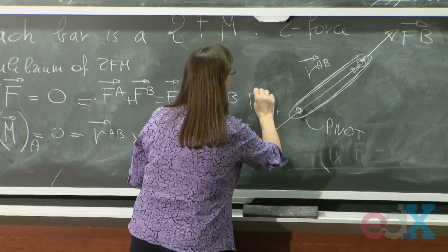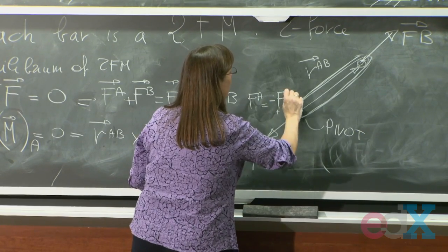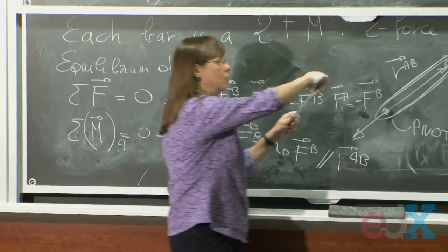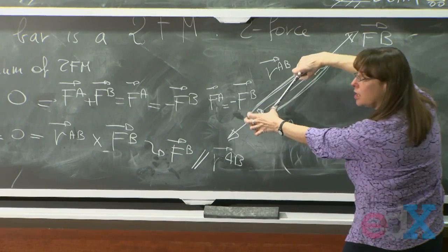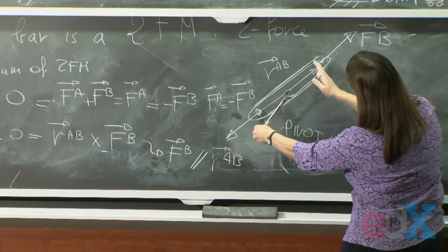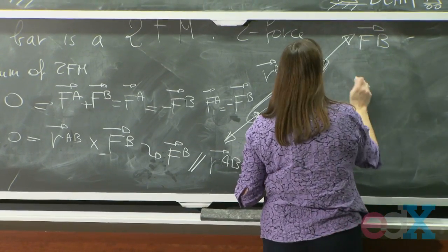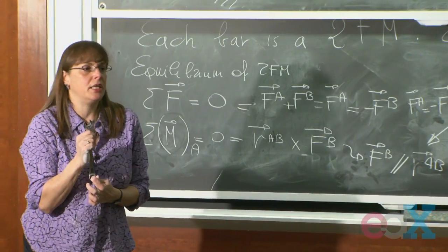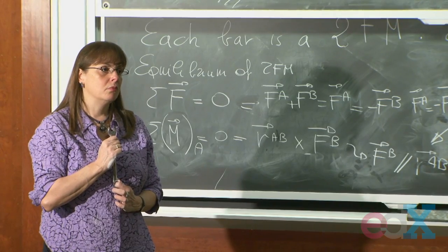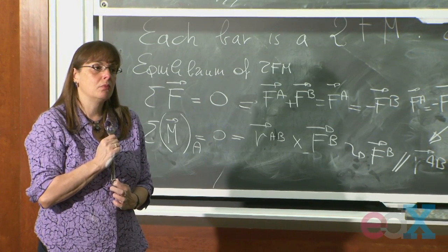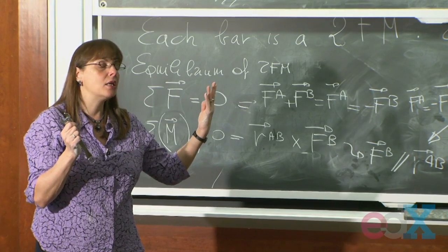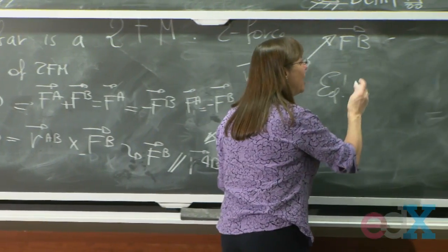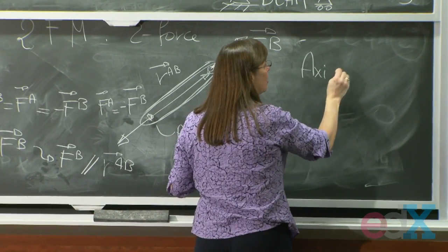And remember that FA is equal to minus FB. So it must be loaded like this. That's the only way that it can stay there and not start moving to a different continent. So it's pulled this way and it's pulled that way, and this is in equilibrium. Okay? So what is the only thing inside this bar? What kind of force? Transverse force? An axial force? You can take hints. Okay, it's an axial force only. The only thing inside the bar is an axial force.